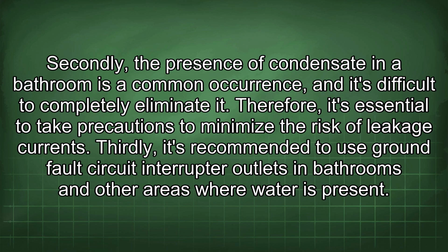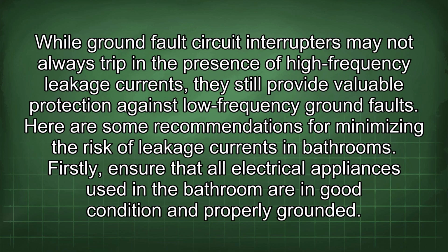Therefore, it's essential to take precautions to minimize the risk of leakage currents. Thirdly, it's recommended to use ground fault circuit interrupter outlets in bathrooms and other areas where water is present. While ground fault circuit interrupters may not always trip in the presence of high-frequency leakage currents, they still provide valuable protection against low-frequency ground faults.